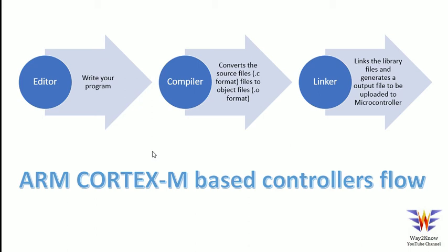This object files format cannot be directly flashed to the microcontroller. You need a final executable to be dumped into your microcontroller for the function to run and perform the required functionality. So in this case, there is something called the linker, which most of the guys are not bothered about, because most of the microcontrollers provide it by default.